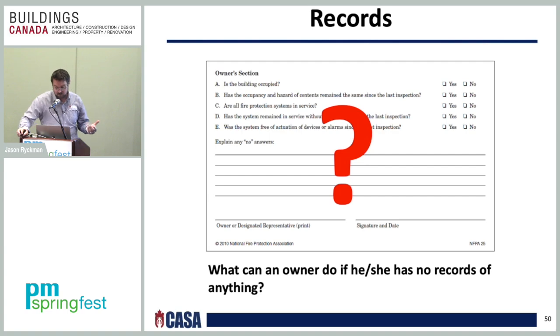Remember that we are operating under the assumption that the system was installed and accepted as correct. It is the owner's responsibility to verify compliance with NFPA 25. The standard does not address the situation where a hydraulic tag is required. Common sense would tell us that it is not required if the system was not hydraulically designed. However, we are simply to verify the presence of the tag. It is the owner's responsibility to provide that information.